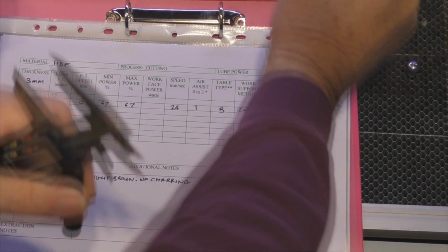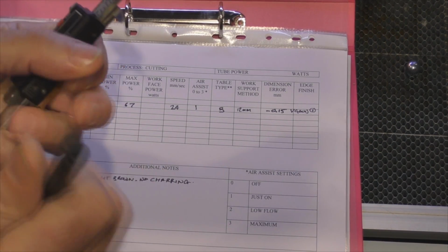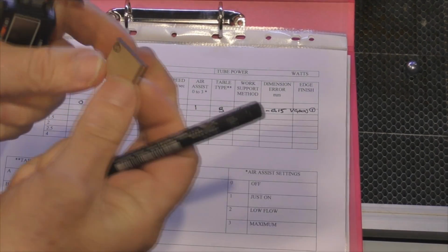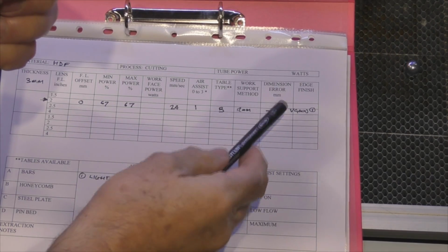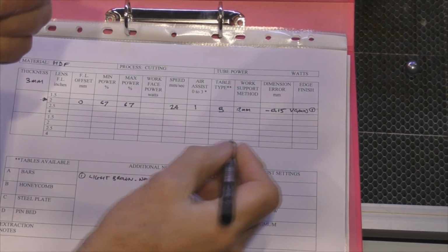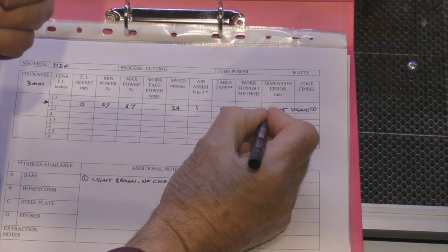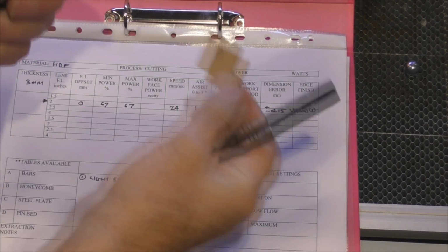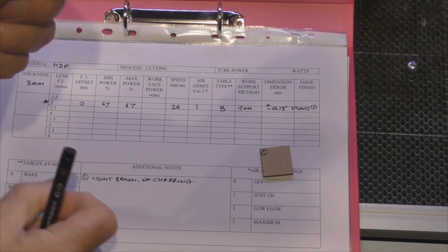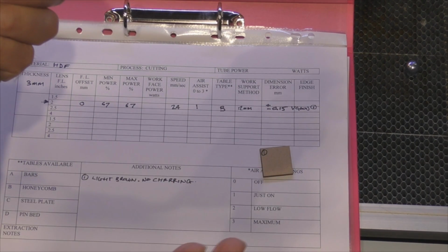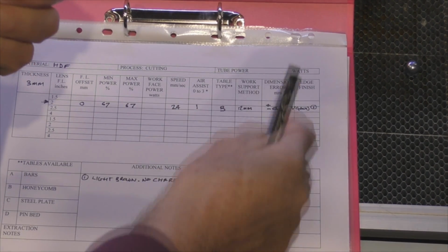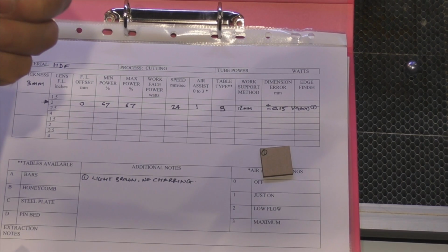0.15. Now that's a very important piece of information, because if you're trying to make pieces that fit together snugly and tightly, you need to know what the error is. Now bear in mind that this is, and I really oughtn't to put, is plus or minus. I oughtn't to put any dimension on that, so it's plus or minus, because if you're producing a shape like this, it's going to be minus, but if you're producing a hole, it's going to be plus. So technically it looks as though that cut width, the kerf, is 0.3. In other words, it leaves a 0.3 gap all the way round.